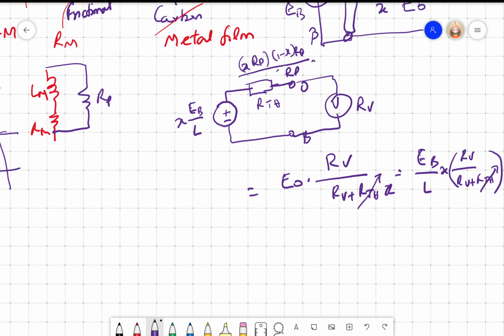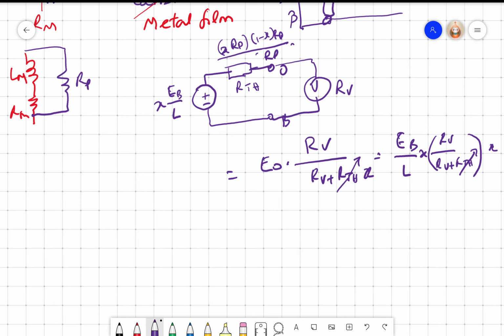That you should understand. So the resistive potentiometer type displacement sensor, both angular as well as linear, is very popular, used in the industry quite a lot. There are only two problems. One is the friction between the wiper and the resistive element, right? So when the friction is there, you'll have to give enough force to move the wiper, which means on the mechanical side there will be loading. Mechanical force is required to move the wiper.